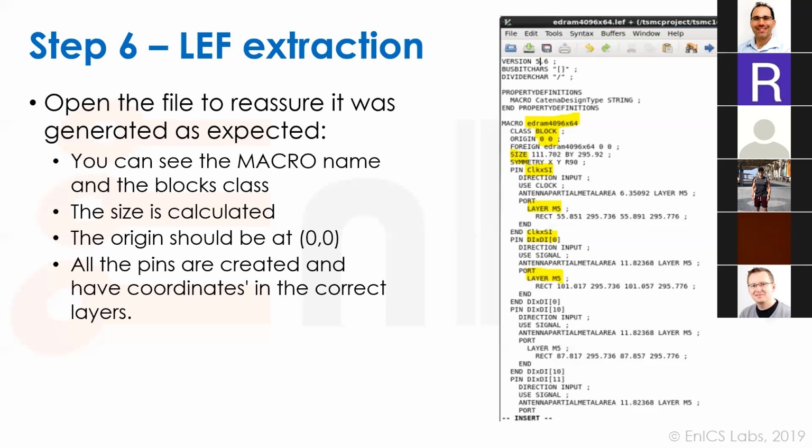But if you need to include the hard macro in your place and route tool, it would not let you do it if you don't have a .lib. Correct. Maybe ILM could stand in instead, but it's an even more complicated thing. Exactly. No, you need the lib and the LEF.